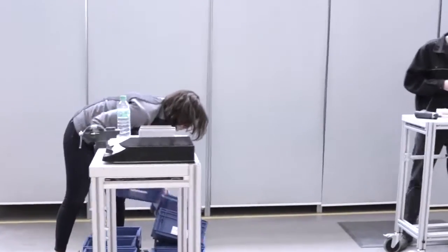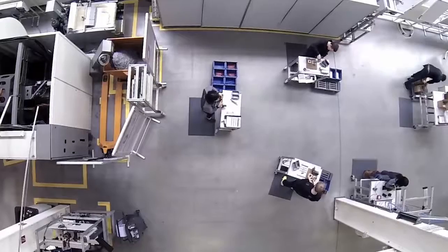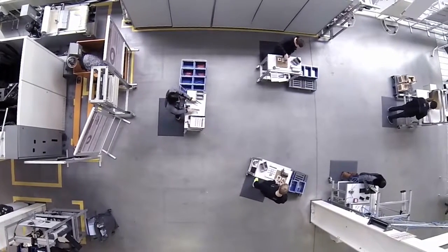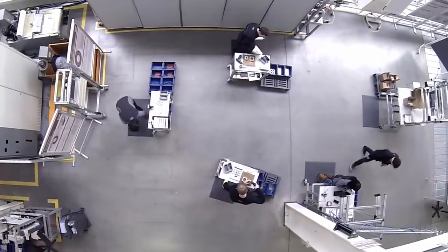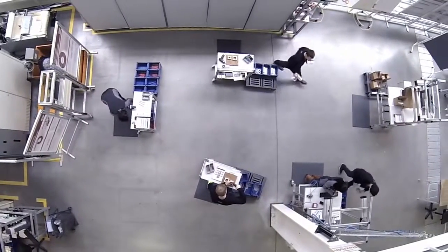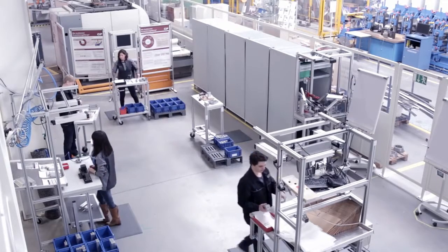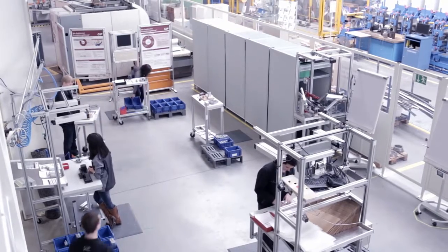In the assembly system shown, several inefficiencies are obvious. The assembly of the product in batches generates unnecessary stock between the assembly stations. The distribution of the working stations creates inefficient transportation distances. Furthermore, the working stations are unevenly utilized, which leads to unproductive waiting times due to missing material. These types of waste can be optimized through a continuous flow production.